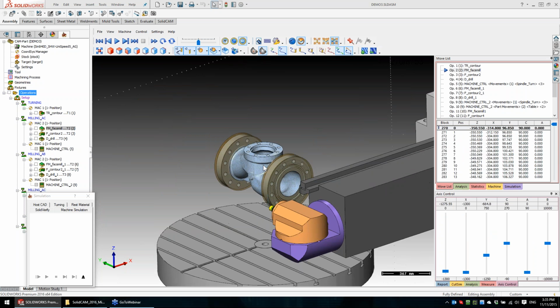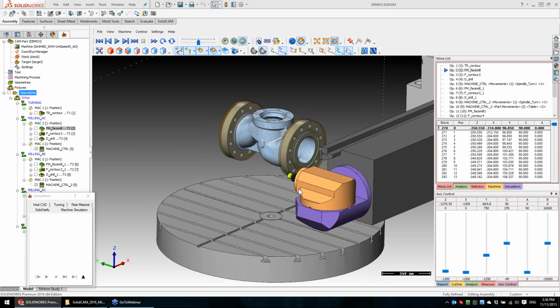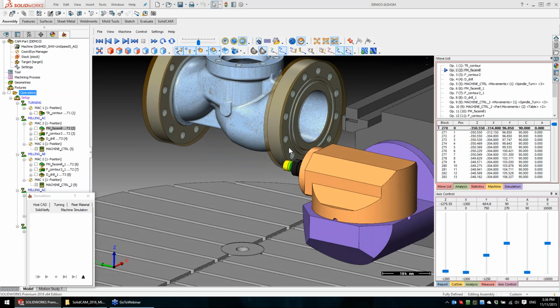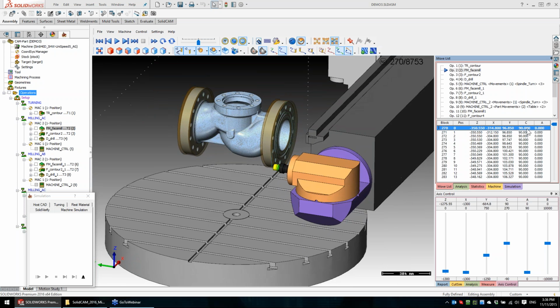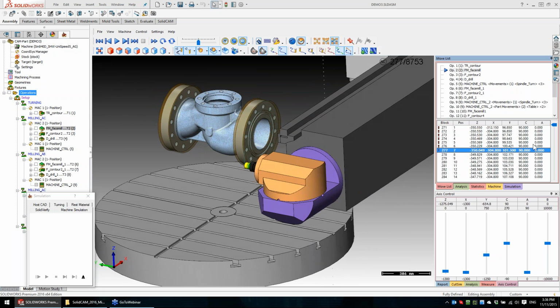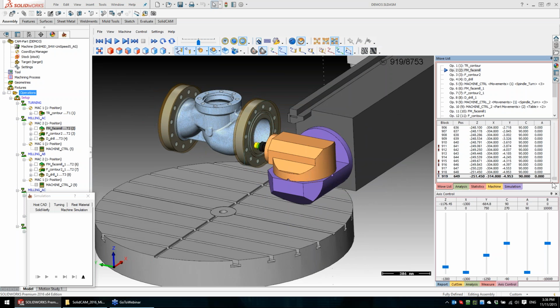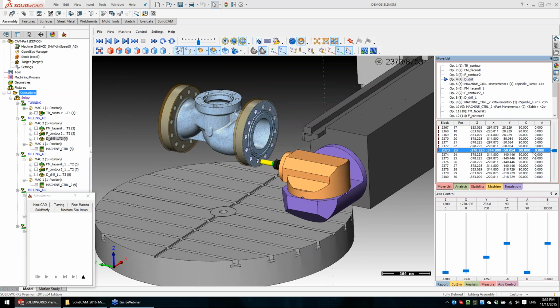Now, after a turning operation, when we clamp this, the table to work on milling is going automatically to 0, to reference. So the table is on 0 degrees. In order to reach this position, this face, the head-head kinematic will have an A0 position, C 90 degrees. Spiral, a contour, and drills. Those are the movements.